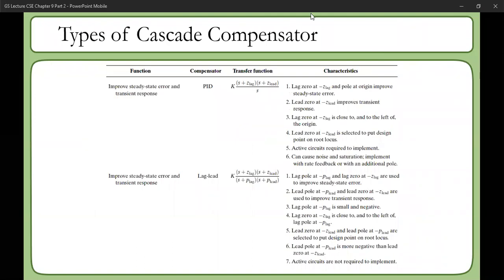Okay, now finally the combination of both of them, improving both transient and steady state behavior. So for that you have the ideal case PID controller. So you're designing something like this. These are for integral. This is for your derivative, and as you can see, they are identical. Okay, so the only difference is whether the pole is closer to the origin or the zero.